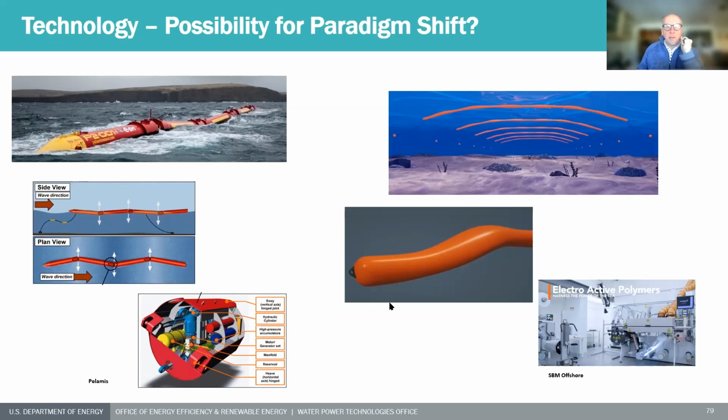They hardly cover the swept area. They rotate over the swept area, but they're completely open, and that doesn't mean that there are losses. It's just a high velocity, low solidity turbine. Guide vanes add complexity, sure, and there are even adjustable guide vanes.